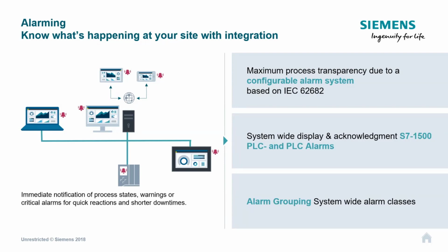When we do all this sort of stuff, it would also be a great thing to deploy alarm grouping and utilize the alarm classes. So we can break these things up into areas of plant or types of operation, like motors, valves, tanks, those sorts of things, in order to filter them in the right way, so an operator can very easily work through all of the alarms and find the issue very quickly.